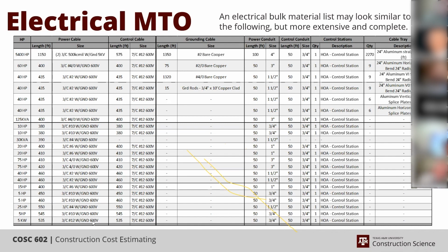Well, it's 600 volt though, so that's not lighting. So they might give you a separate breakout in here for your lighting utility cable, or if you're running through here and you see you're dealing with your 10 and 12 gauge and it's dropping down to 120 volt, now you're back in your lighting and your utility. This 600 volt is all going to be process equipment.